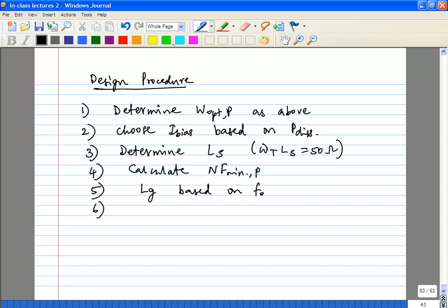Now you have the transistor and you're going to add the cascode most probably. Cascode adds a lot of benefits, so you're most probably going to add it, and I'm assuming that you'll start off with a cascode the same size as your main transistor. Okay, that is given. So then the next thing to do is choose the load.